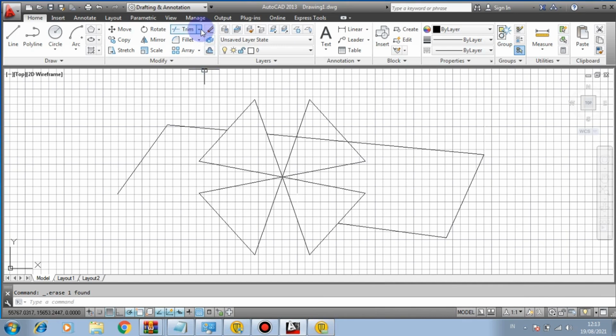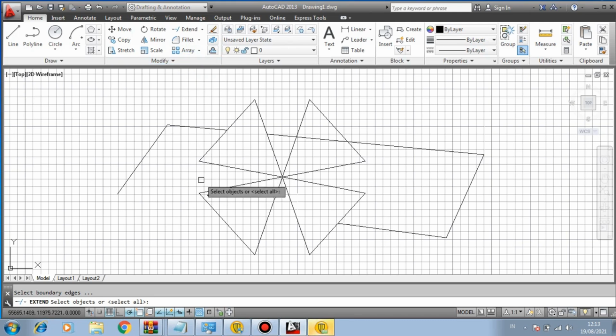First, click extend. Then click the boundary. Click, press enter. Finish with enter. Click the line you want to extend. It will stop here. If I click again, it will extend further. Click. As long as there's a boundary, it will keep extending. That's how you use extend.